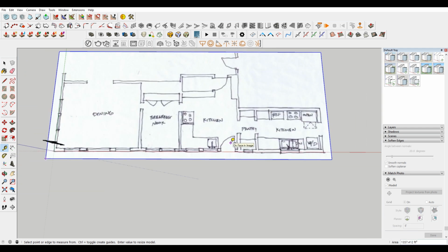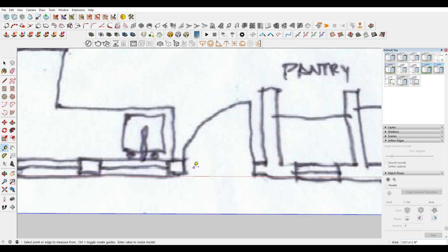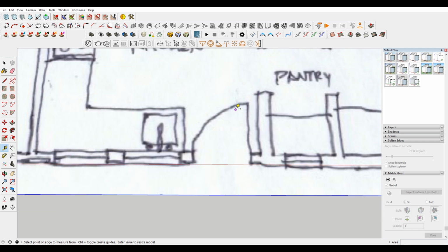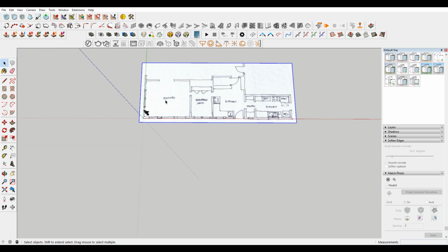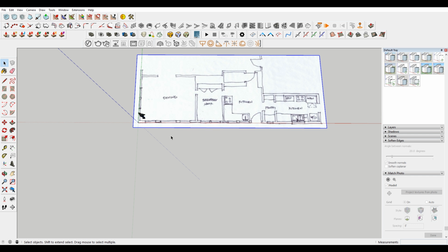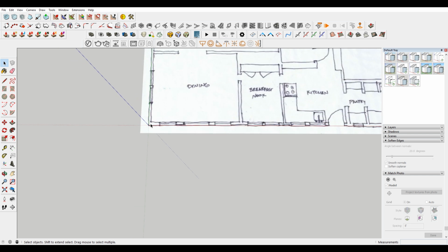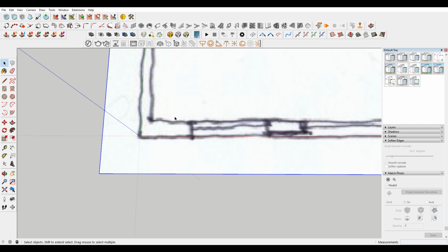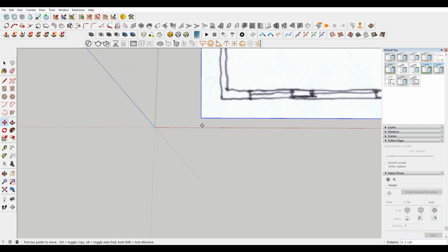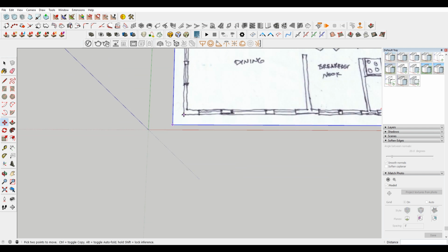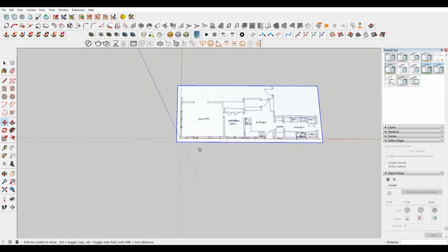And if you didn't see what I just did there, I took my tape measure tool, I went across here, and then I clicked, and then I typed in 36 inches and hit enter, and it let me scale that. Now what I always like to do when I am drawing something like this, let me just delete the scale figure, is make sure that I have a point of reference at my origin that makes sense. Typically that'll then help me with everything.